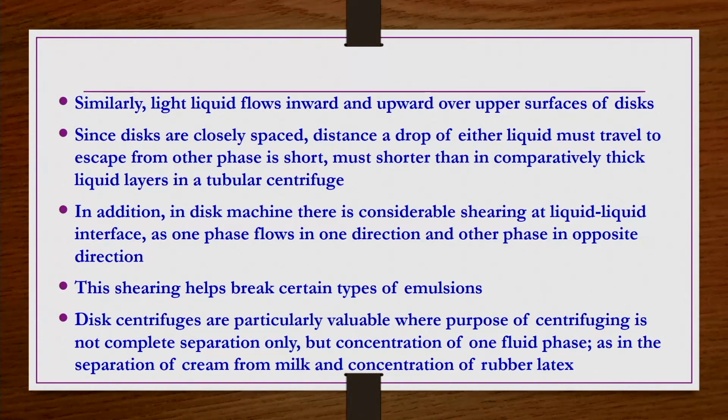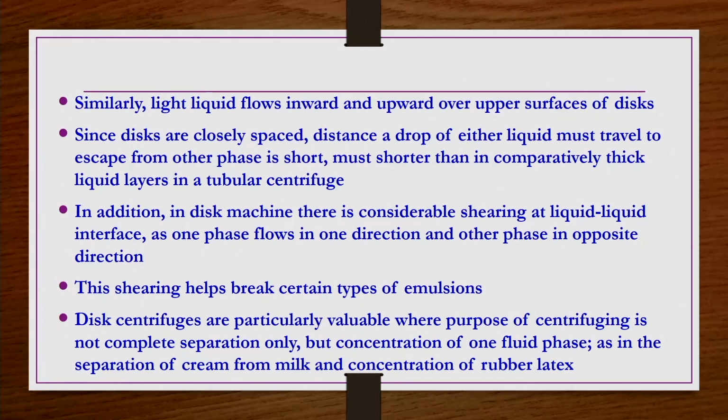Because of this, the shearing helps break certain types of emulsions, if at all they are existing in the feed system. Disc centrifuges are particularly valuable where the purpose of the centrifuge is not complete separation only, but concentration of one fluid phase, as in the separation of cream from milk and concentration of rubber latex, etc.